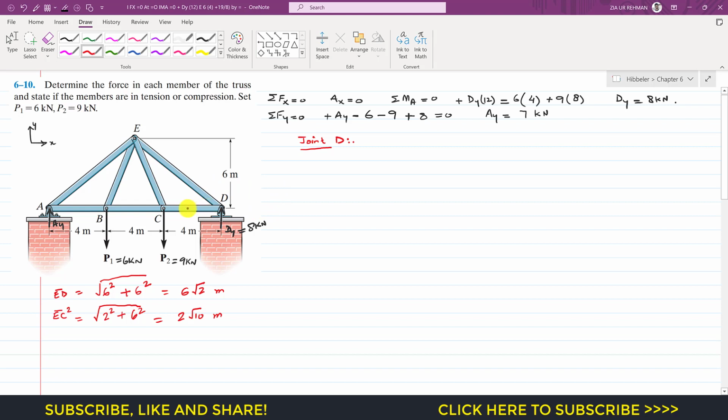here we will have this CD member force. Let's say that the force in this CD member is acting in this direction. This is that CD force, and we are assuming that this CD force is a tension force since it is acting away from the joint D, and let's say that this is the DE member force. So this is DE. I am not going to write FDE. So DE will mean the DE member force and CD will mean the CD member force.